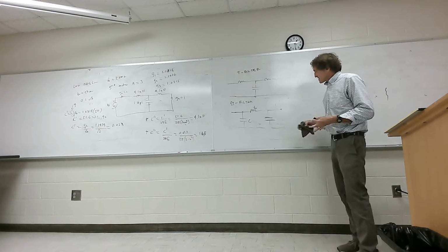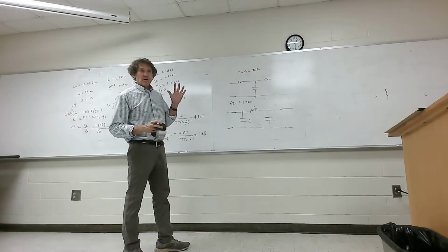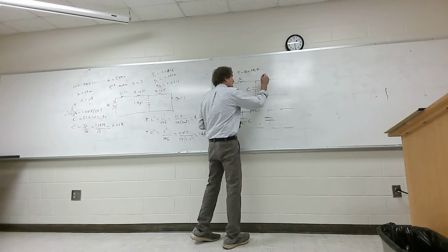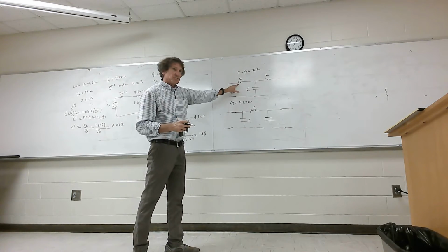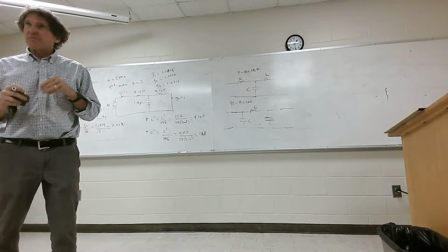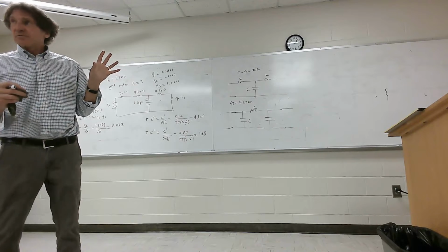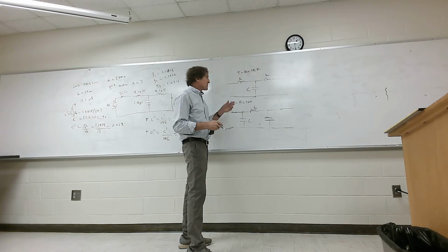Now, if you look at this and this, they're both low-pass filters, and if you use those tables to get the values of L and C, remember this is G1, G2, and G3. If you use the actual values of G1, G2, G3 from the table, you'll get values that you have to transform using the characteristic impedance and the cutoff frequency. You'll get these values, and if you ran the performance of these two filters, they're identical, which is interesting, because I wouldn't think that off the top of my head, but they are. They'll give you the same insertion loss at 50 ohms.